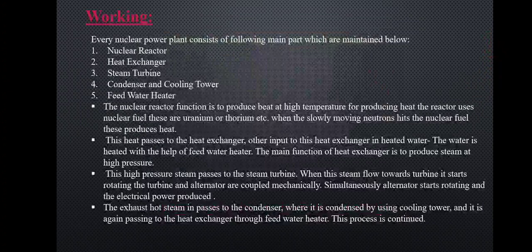Next one is the cooling water or cooling tower. After absorbing the heat from the exhaust steam, the temperature of the cooling water increases, making it warm or hot water. This hot water is sent to the cooling tower where it is cooled. The cooled water so formed is again sent back to the condenser with the help of circulation water pumps.